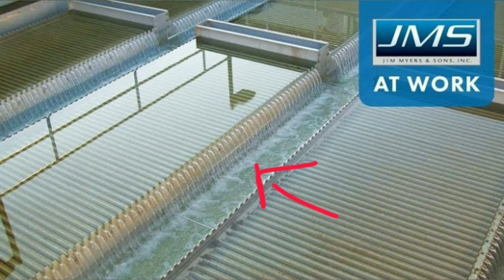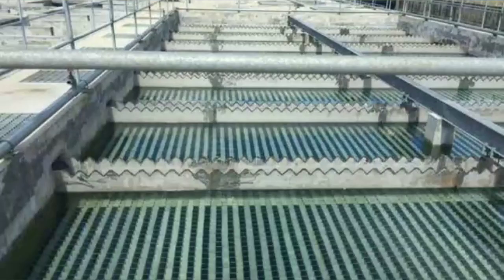Because of that, we can expect a longer life when we compare to the tube settlers, and the maintenance is very much low. And when we compare this with the regular sedimentation tank, maintenance, cleaning, and other operations and inspections are also very easy. Here we can see the next type of settler, that is, a tube settler.